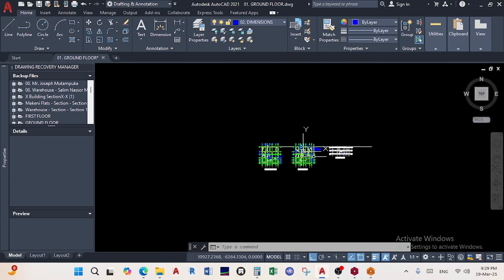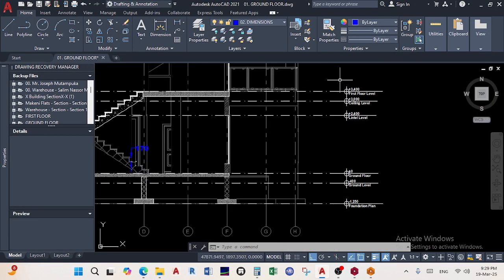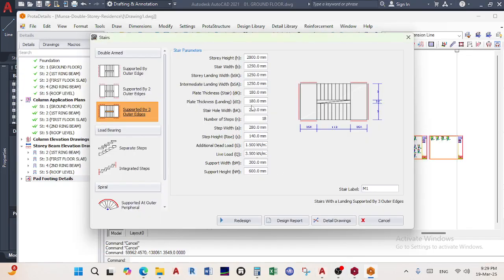Let's go to our section view. We check. This is 3 4. This is the top. This is 400. So from 0 to it's actually 3000. So here I'll change my information. I'll say my story height is at 3000.